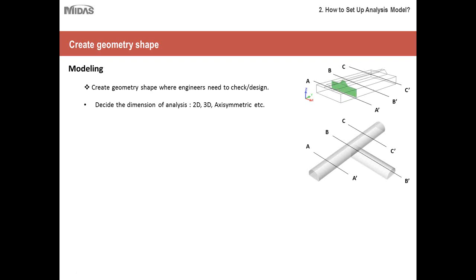So it really does not matter if I do a 2D analysis or a 3D analysis. If I have to save time, and if I want to run something quick, I can quickly create a 2D model for this type of structure. When your dimensions are not changing along the longer axis of the structure, then 2D analysis is sufficient.